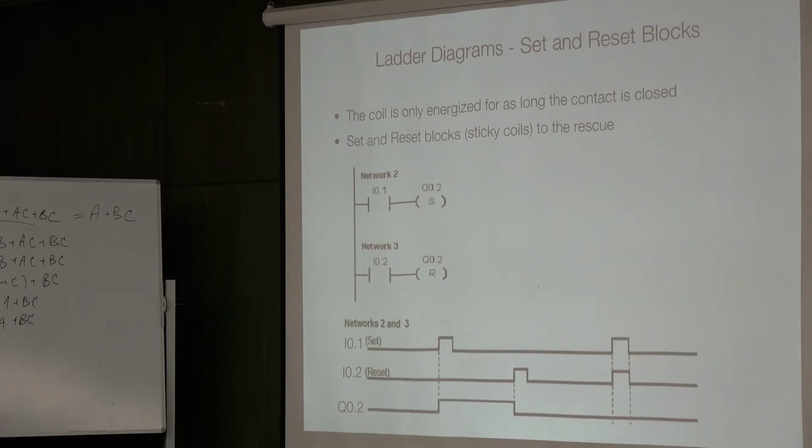So it's just a physical mapping between the physical arrangement of the PLC and the internal memory of the PLC. Basically, you have to know that this is the second, no, it's actually the third one, because everything is indexed from 0, right? So Q0.0 would be the first digital output. Q0.1 is the second digital output, so this is the third digital output in your kind of rack of input connectors.